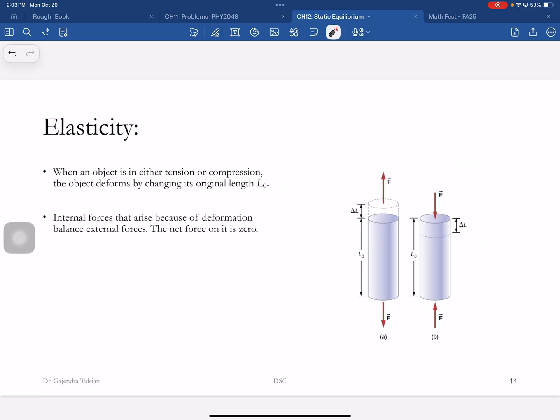All right, here's another thing I want you to understand because I'm going to zip through these slides. This is a tensile stress. A tensile stress is when you're lengthening the structure. This is a compressive stress. It turns out that a lot of materials are strong under compressive stress. They're weaker under tensile stress. Your bones are stronger against compressive stress than tensile stress. Concrete is almost 10 times stronger under compressive stress than tensile stress.